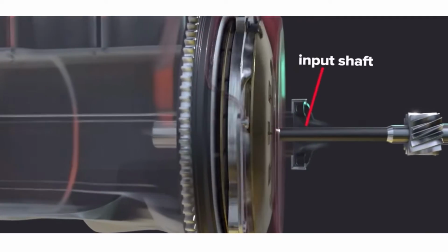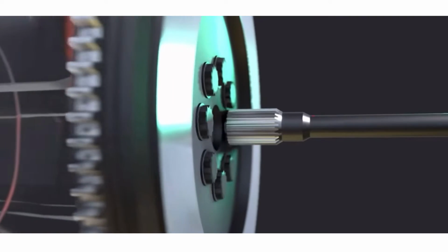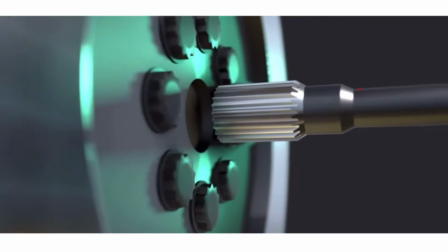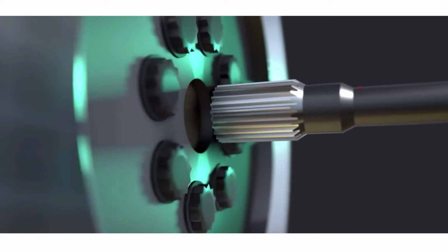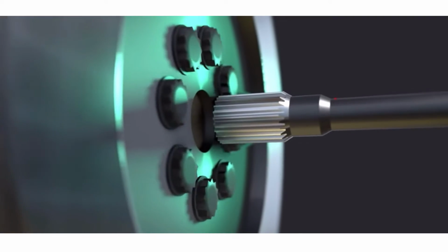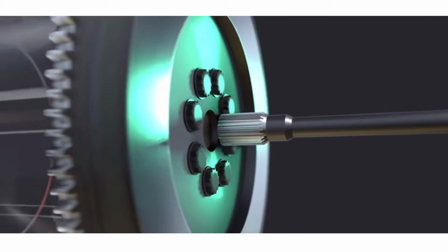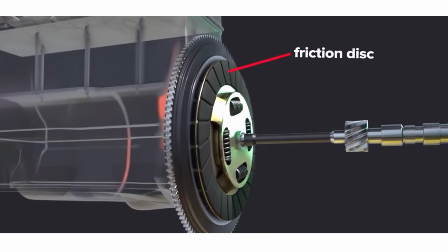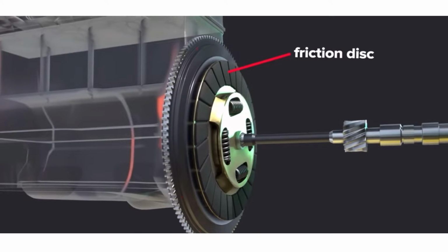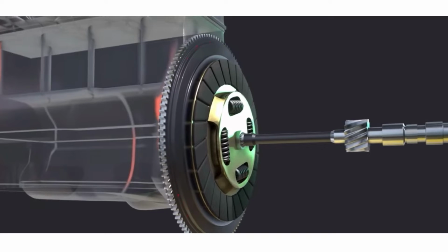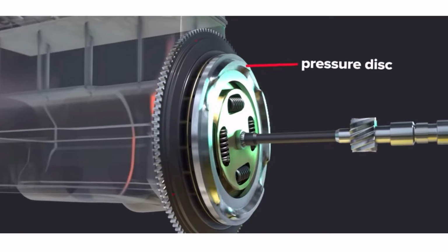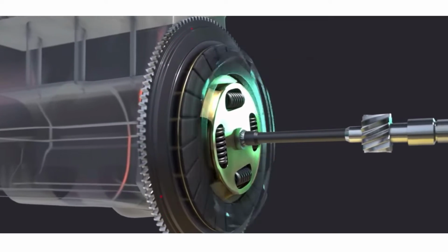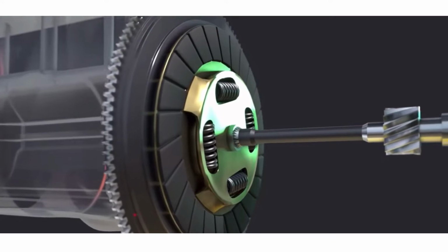3. Flywheel. As it relates to manual transmissions, the flywheel is the component which delivers engine torque to the clutch disc. This circular mass has a smooth surface which the clutch disc interacts with. Understanding how a clutch works is fairly important to understanding the transmission overall.